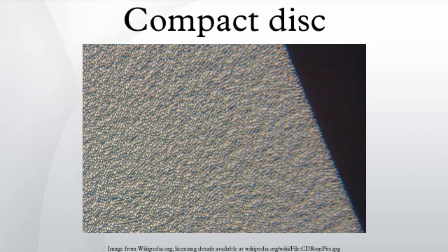A disc with data packed slightly more densely is tolerated by most players. Using a linear velocity of 1.2 meters per second and a narrower track pitch of 1.5 micrometers increases the playing time to 80 minutes, and data capacity to 700 MB.